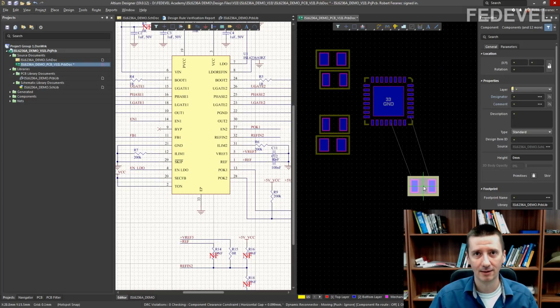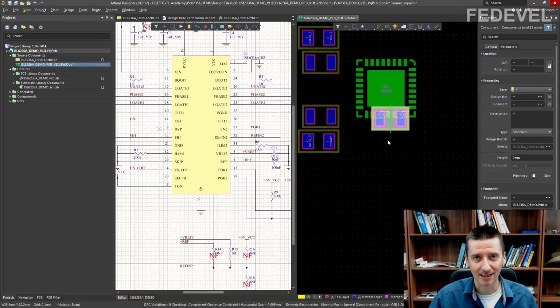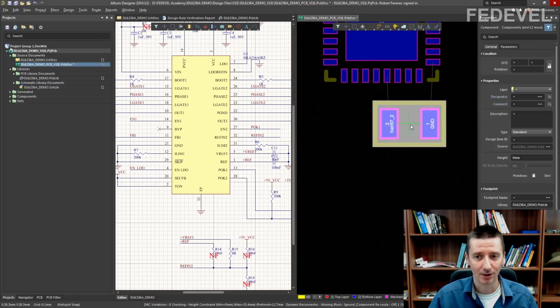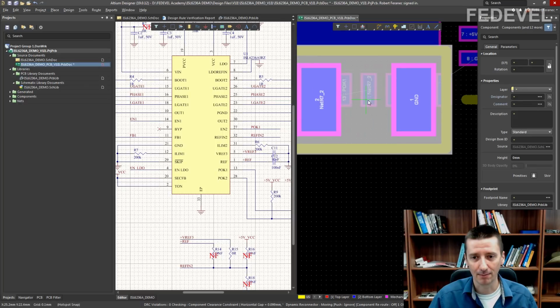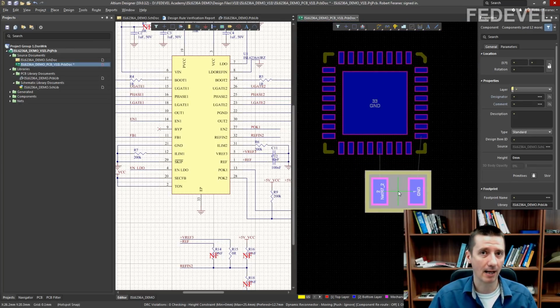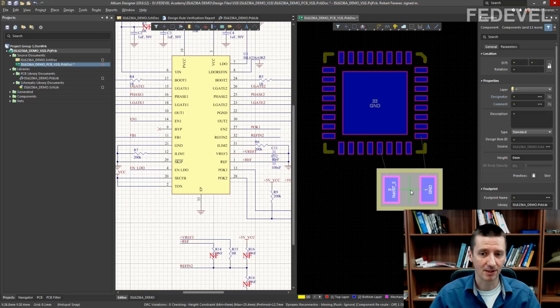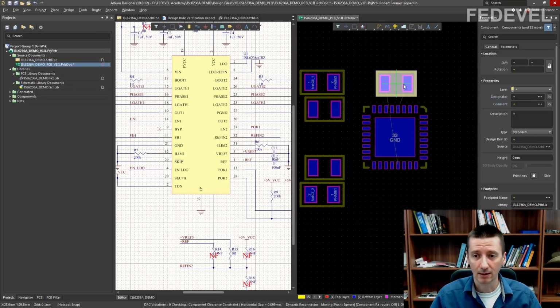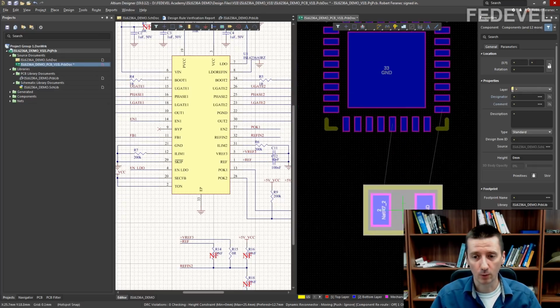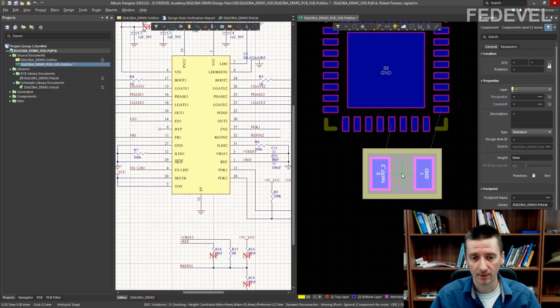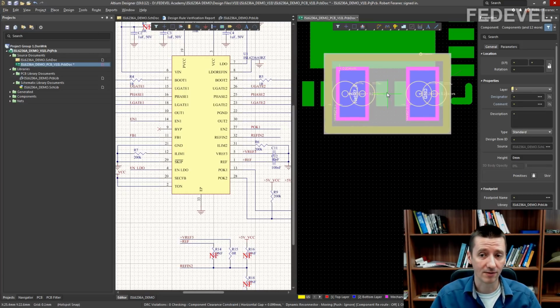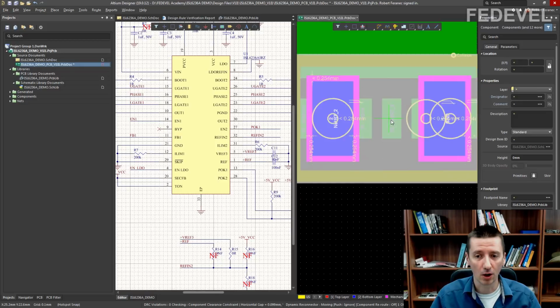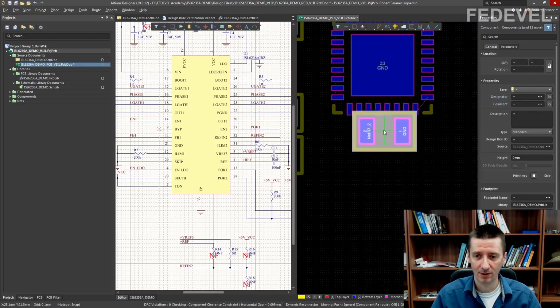Do you know why? Because this one which stays here is the important connection connected to pin number 12. See, pin number 12. The other one is just ground, and ground is all around the PCB, so it's not really important where we place the ground connection. It is important where we place this resistor. We need to place it close to this connection, which is always fixed. We need to place it close to this pin number 12.